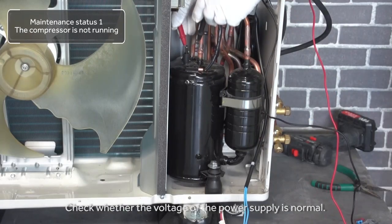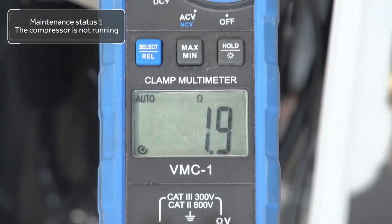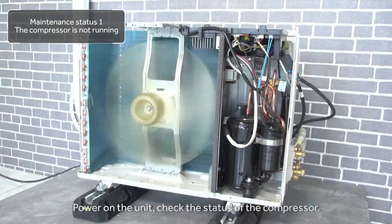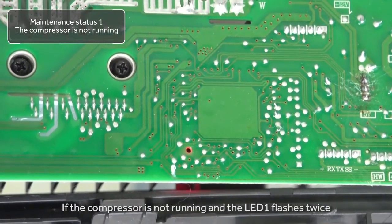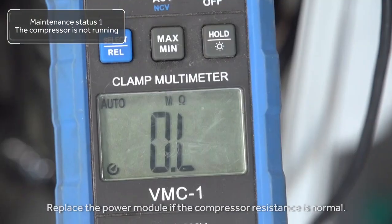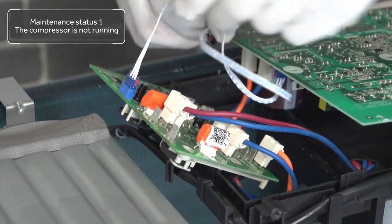Check whether the voltage of the power supply is normal. Power on the unit. Check the status of the compressor. If the compressor is not running and the LED 1 flashes twice, replace the power module if the compressor resistance is normal.